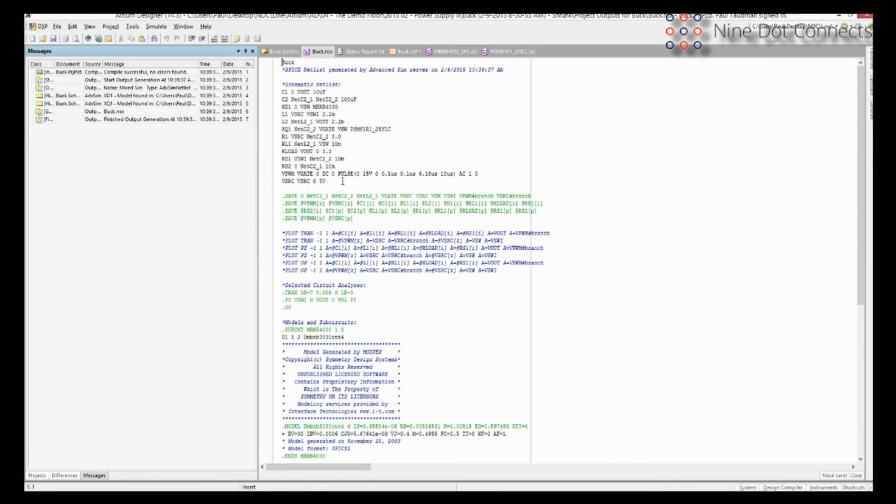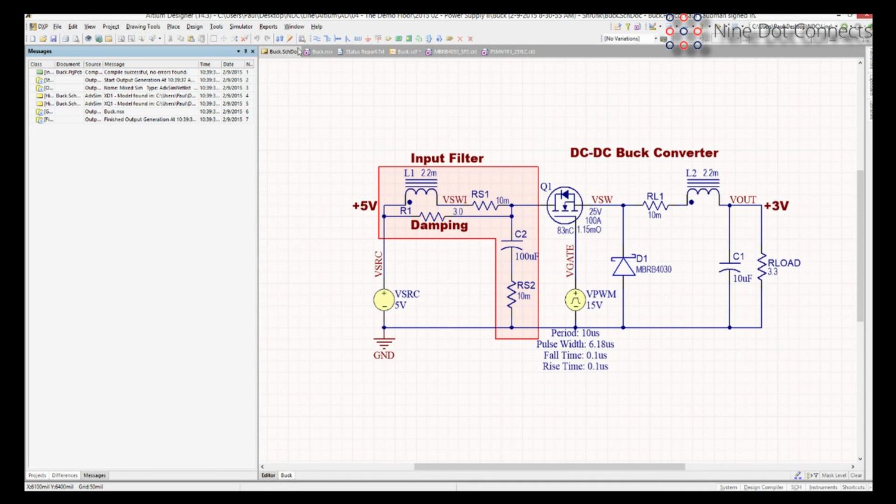In theory, this could be ported over to another SPICE tool. It's using all of the commands that SPICE comes with. Okay, but there can be some variances and differences. Again, after that big split between PSPICE and Berkeley SPICE, there are differences that some tools can read in, some tools can't. They may ignore them, and so on and so forth. So, for example, if you were to try to pull this one into LTSPICE, most of it will read in, but my understanding is that there's going to have to be some cleanup. So don't expect everybody to be universal in that nature. So it will create this for us. Let's go back to the schematic document.